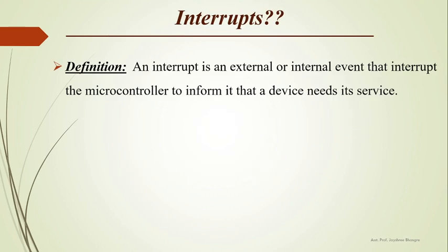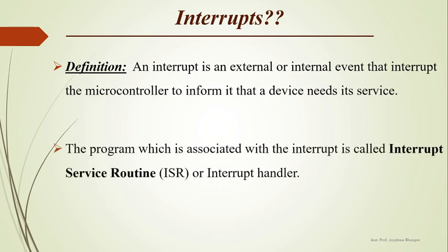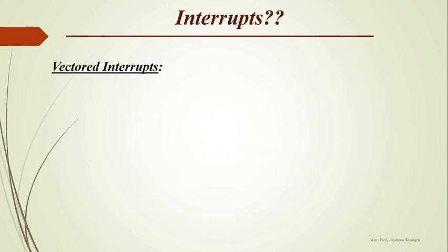An interrupt is an external or internal event that interrupts the microcontroller to inform it that a device needs its service. And the program which is associated with the interrupt, that is the small program written for that interrupt, is called interrupt service routine, that is ISR, or interrupt handler.